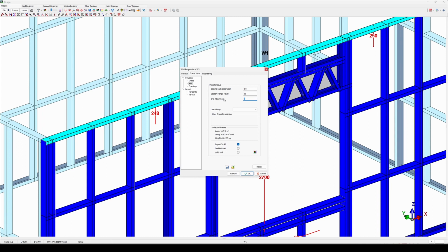to another wall, let's say for example you have a 6-meter length of your wall, it will in actual fact be 5.999 meters. The reason for that is again for tolerance where you have one C-section connected to another.